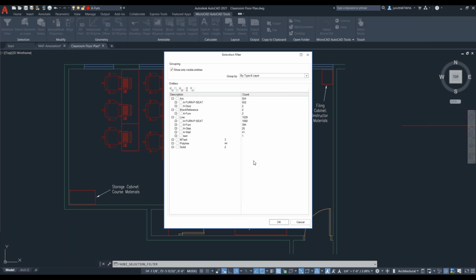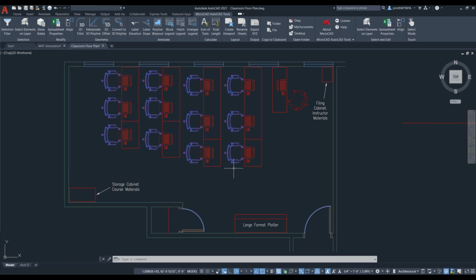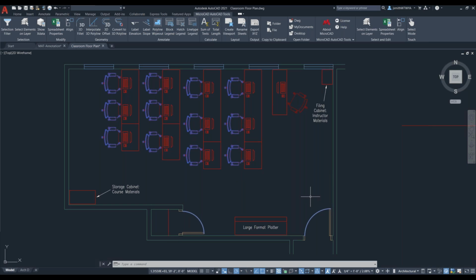And then if you want to select those objects, let's say I wanted to select those arcs, regardless of what layer they were on, I just wanted to know every arc that was in my plan. I could click that checkbox there and it highlights both of those layers for me. I click OK, and it goes through and finds all the arcs in my plan. I've got some door swings here, and obviously a lot of the objects on this chair block have a lot of the arcs from my plan. It's amazing when you see it written that way, that there are over 500 arcs in the plan, but it gives you a good perspective of what's happening in your drawing. And again, this is a really small plan, so it's still amazing that you have that much going on.